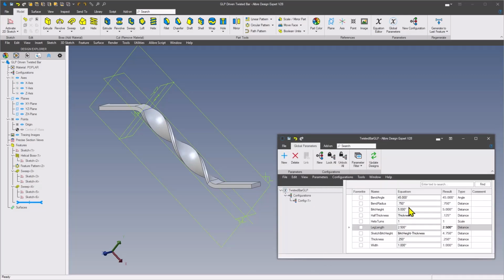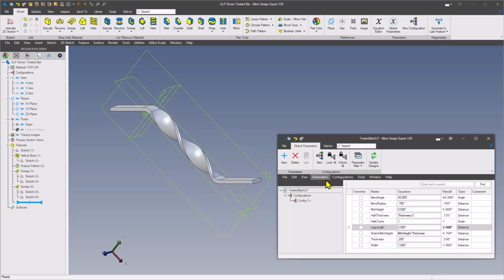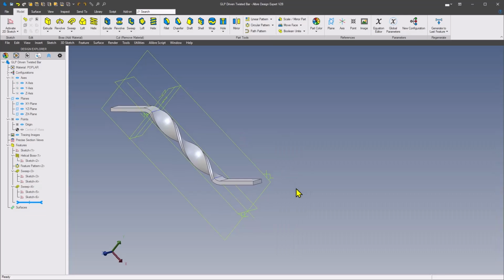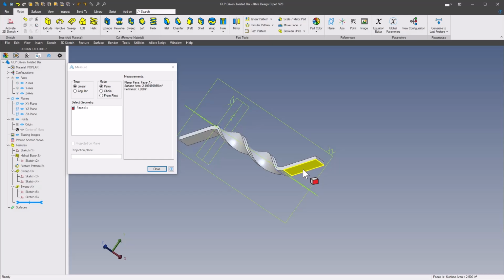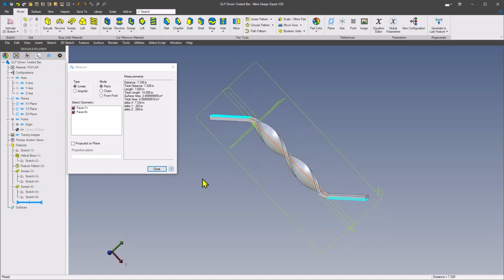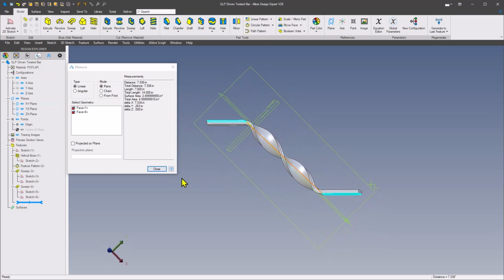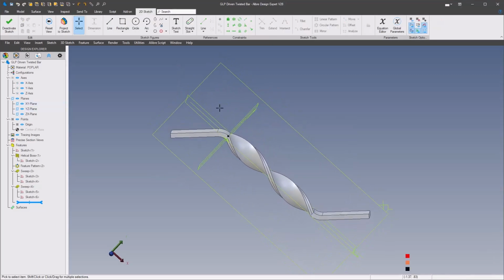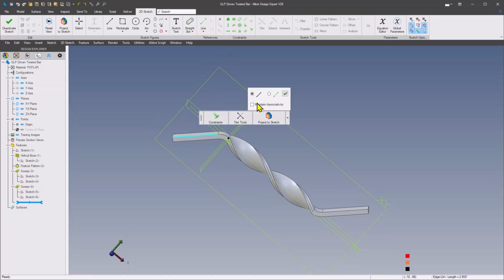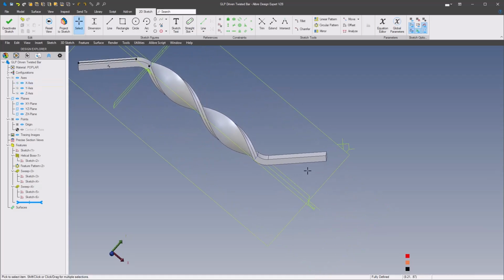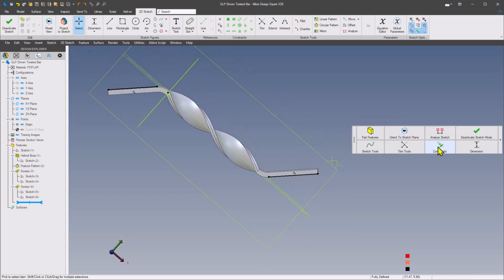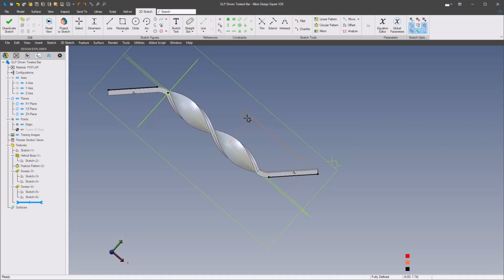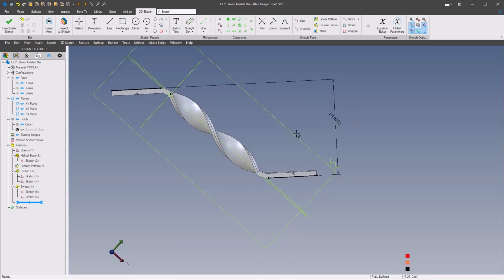So at any rate, one more here. We've got a bend bracket height. We're at 5 inches. Let's just take a peek here and see what our height is. So if we click on this angle and this face here, that's going to be a line to line. So let's do this. We'll come in and grab a sketch, and we're going to project this line, and we'll project this line, and we'll throw a dimension on here, and then we have 5 inches.